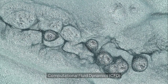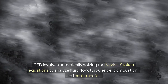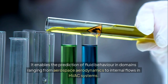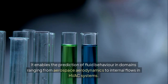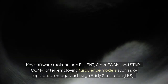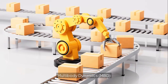Computational fluid dynamics, CFD. CFD involves numerically solving the Navier-Stokes equations to analyze fluid flow, turbulence, combustion, and heat transfer. It enables the prediction of fluid behavior in domains ranging from aerospace aerodynamics to internal flows in HVAC systems. Key software tools include Fluent, OpenFOAM, and STAR-CCM+, often employing turbulence models such as k-epsilon, k-omega, and large eddy simulation, LES.